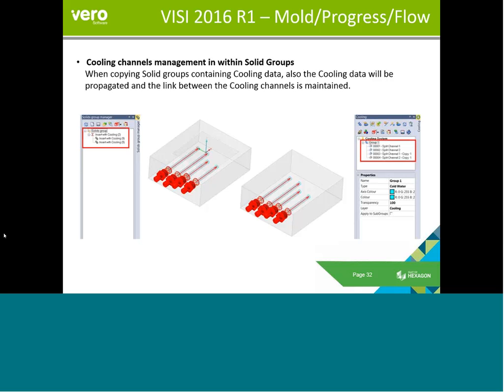After a CAD transformation on a cooling circuit, say just a translation, for example, the system will automatically update the relative cooling tree structure in reference to the modification done. Copying the channels, the system will also automatically add them to the cooling tree. And you can see an example of that on the right-hand dialog box where we can see a copy 1 created.